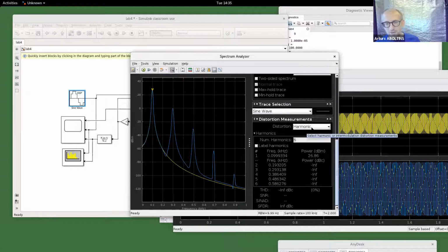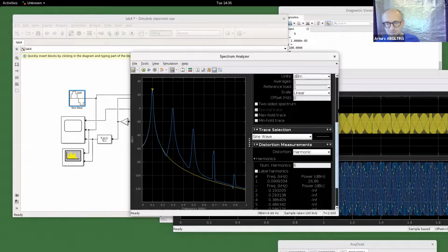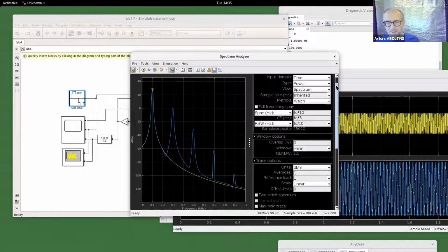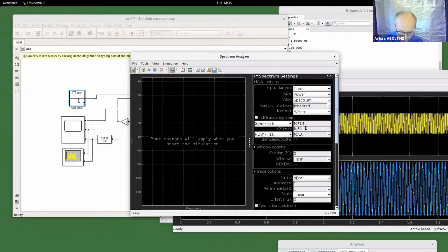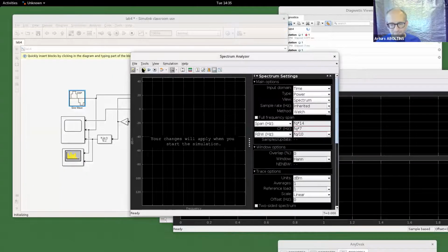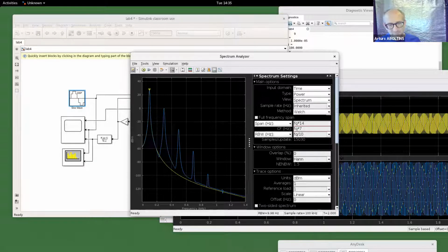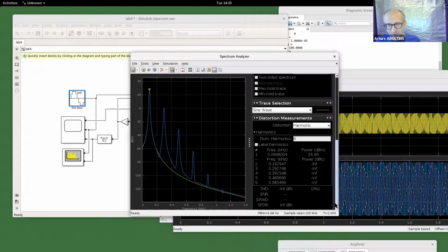it's not enough harmonics, like 6 harmonics, we need a larger frequency span. Either we decrease the number of harmonics, or we could increase the frequency span, like let's say 12, okay, or even 14, because in this case we are pretty sure that it will be 6 harmonics.